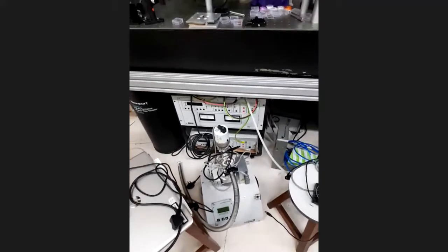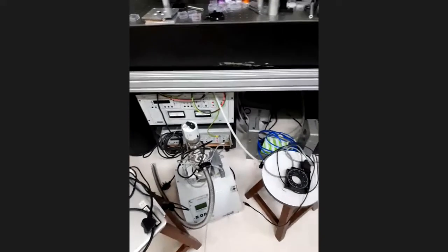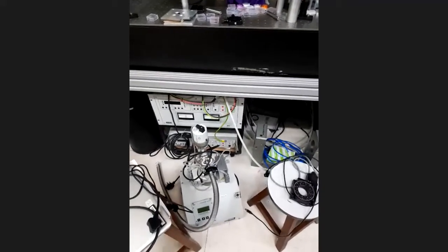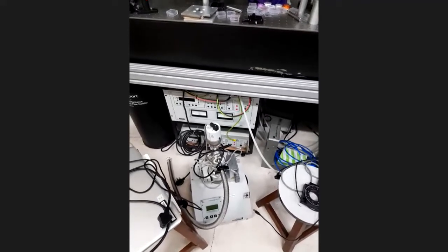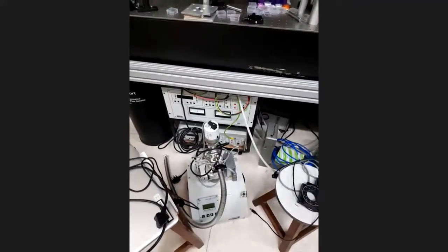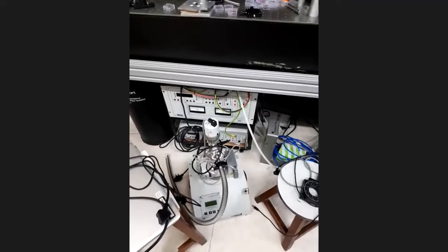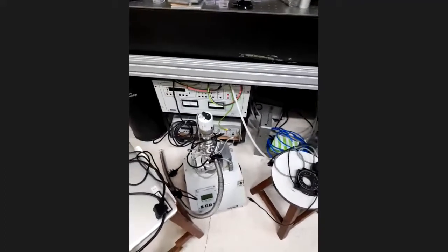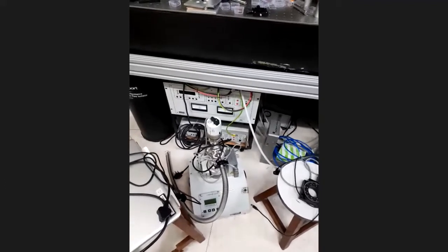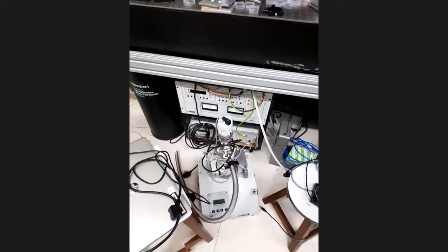So if we don't evacuate and we start putting in liquid helium and try to lower the sample temperature, the air molecules start becoming liquid. Liquid droplets will form on the sample and all around the cryostat. You don't want that. So you pump all the air out.